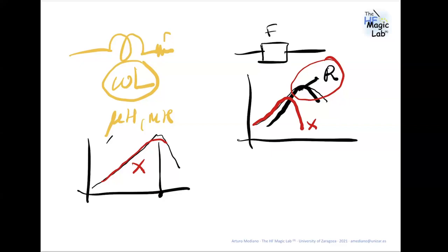In the case of an AC-DC converter, when the heat sink needs to connect somewhere to avoid EMI, where should it be connected? Considering that the heatsink is working with power devices, the general answer would be to the power ground.